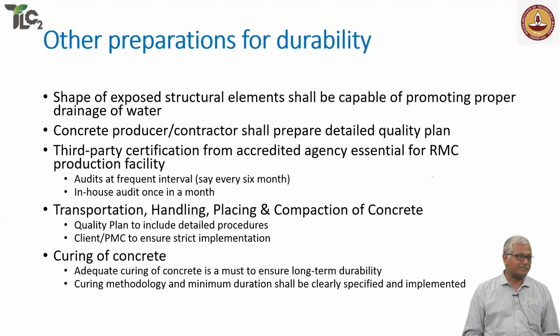Anyway, then finally, the curing of the concrete. Adequate curing obviously is a must. You need to ensure that the curing strategy is designed properly and implemented with proper supervision on the site, right? Because there's only so much we can design. Ultimately, the control of how the application process on the site is in the hands of people who are not very qualified. They are simply there doing the work, but they need to be brought in to understand the importance of that work. That's the last line of defense, right?